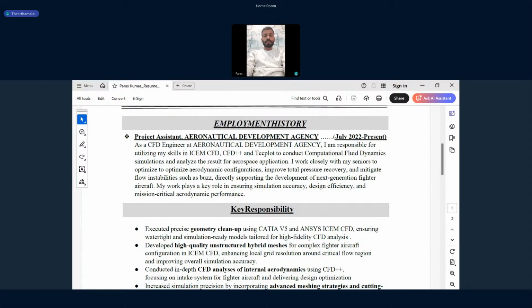So normally for rockets, what do they use, a convergent divergent nozzle or only a convergent nozzle? Rockets, solid propulsion, convergent. So for high propulsion, in convergent divergent nozzles, shock will come. In the convergent divergent nozzle, where will the shock come? In the divergent section.